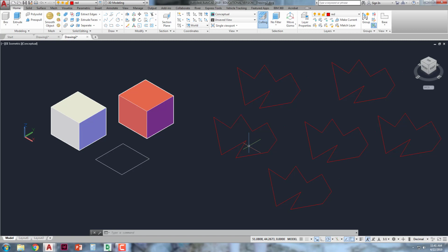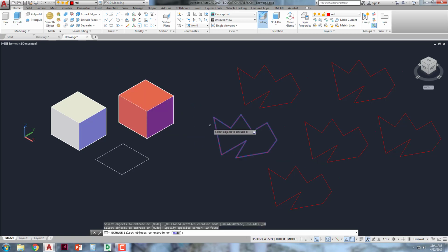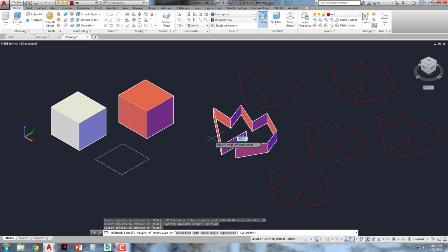What we're going to do is take your flat 2D stuff that you've drawn and extrude it. We're going to give it depth along the Z axis, and that's going to make it 3D. But let me show you the extrude command. It's this guy right here, extrude. I'll select those objects as what I want to extrude. Watch what happens. Is this making it 3D? It is 3D. It's got some depth along the Z-axis, but it's not making it into a 3D solid. It looks more like a cookie cutter, right? What I want is for it to be solid.